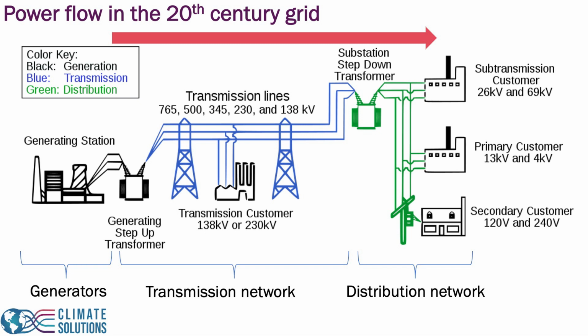Larger customers, such as factories, which are typically a sub-transmission customer, or even a collection of commercial buildings like a campus, which typically is a primary customer, will interface at this system at higher voltages. But they will have internally their own transformers to finally bring down the voltage of the power being consumed to this 120 volts, 240 volts range.